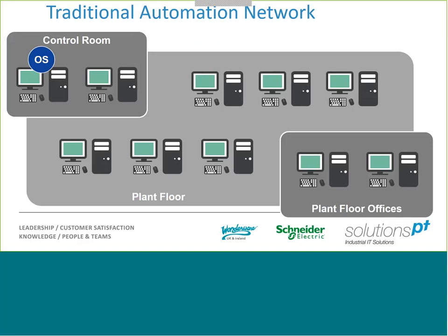It could be that some people have got XP, Windows 7, different instances of it. You've also got your applications, so again, it could be that you've got InTouch or System Platform or whatever it might be. Again, you might have InTouch at a certain version on one machine that differs from another, making sure that if one of those machines fails, that you've got the right version of the application installed. We've also got some antivirus living on each machine.